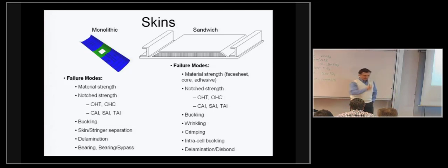Basically, you exceed the strength of the material, whatever constituent it is that might fail, fiber or matrix. But that is usually not even of interest, because you have to design the so-called damage tolerant design. You have to design with typical damage present, because it's unavoidable that this will happen.